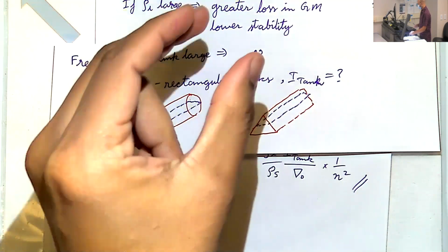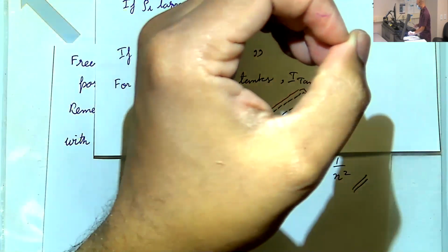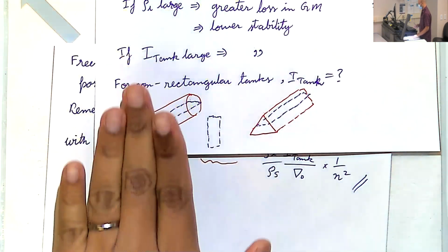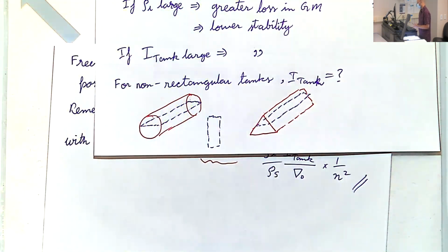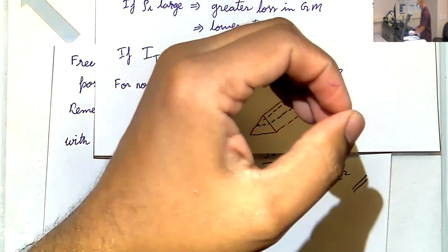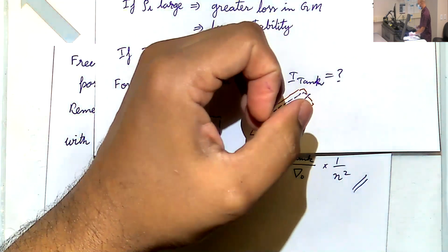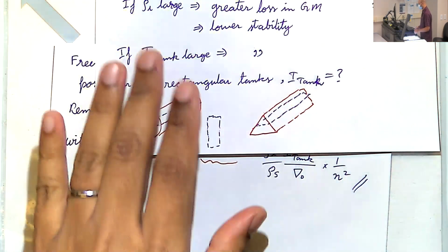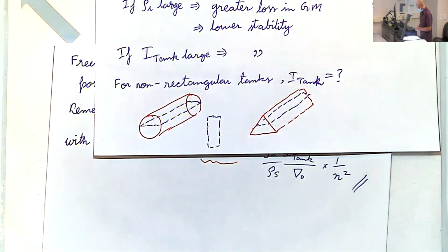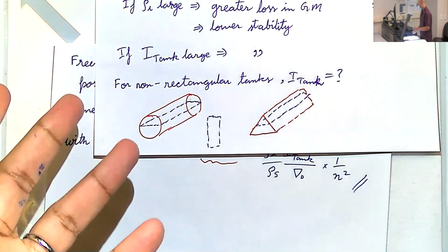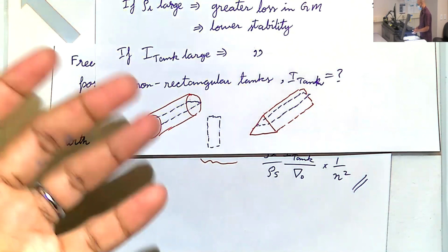Also, you're concentrating all this heavy liquid in one position instead of distributing it throughout the hull, okay? So there's always pros and cons. That's the biggest con, that you're basically putting a very heavy weight in one location instead of letting it slide all over the hull, okay? But what you proposed is an effective solution.